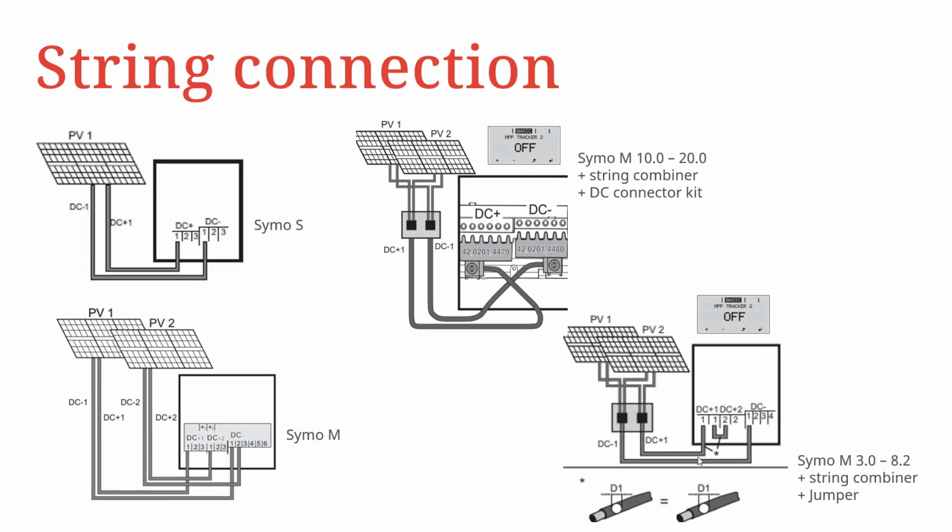Another important note is when you are pre-combining and you don't have the DC disconnect kit, you will be able to use a jumper cable. So this is when you are simply doing a connection from your DC1 positive and obviously your DC negative, but you'll have a jumper lead from 1 to 2, so you're effectively achieving the same principle as your DC disconnect, in a sense, and also to ensure that your MPPT tracker 2 is off when doing any pre-combined systems.